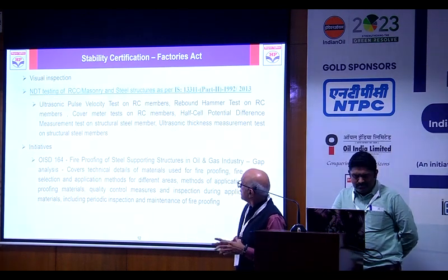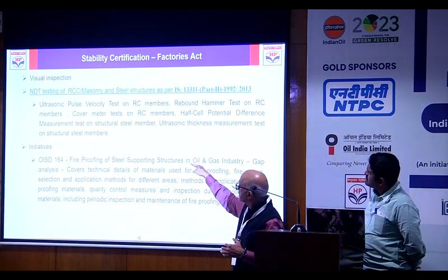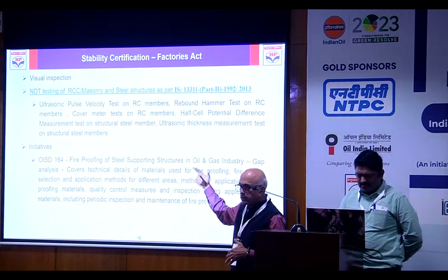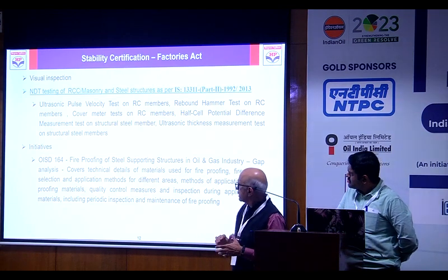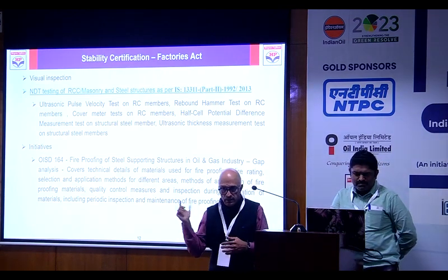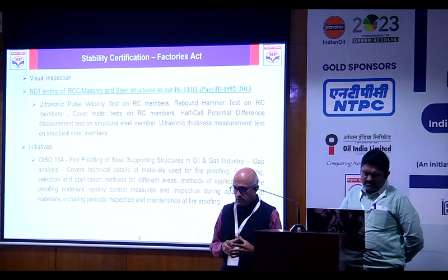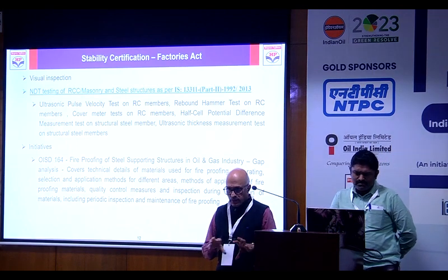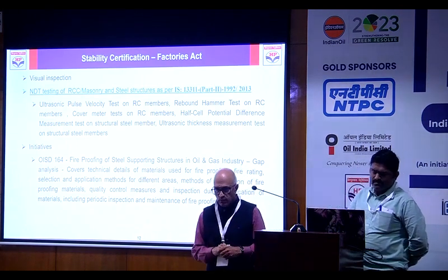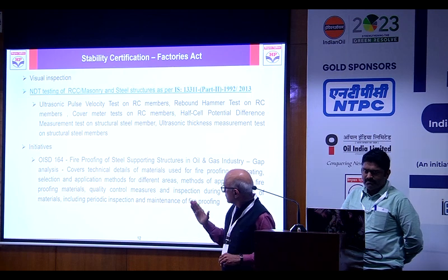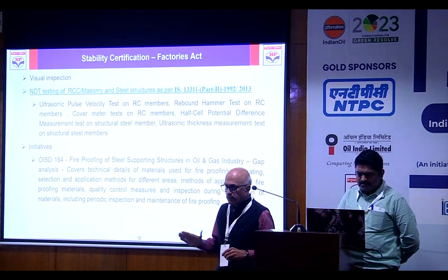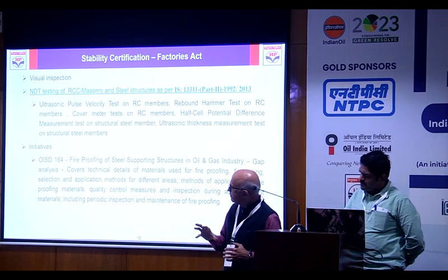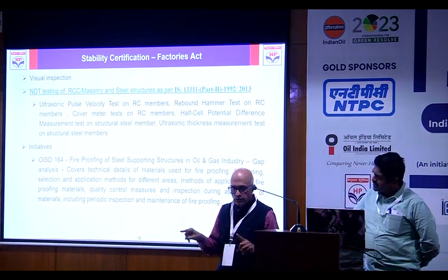Next. In addition, these are the structural integrity tests, as I told earlier. Similarly, they do that for certifying, and once repairs are carried out, they will give validity for 3 years. We took an initiative for OSD 160 for pipe, this guideline, to carry out a gap analysis. As per OSD, what is the requirement and what is the current status, because many units were constructed before OSD came into the picture. So the gap analysis we completed and started restoring fireproofing, or providing fireproofing where it is not there. So structure and fireproofing along with the equipment should be considered in its totality. Next.